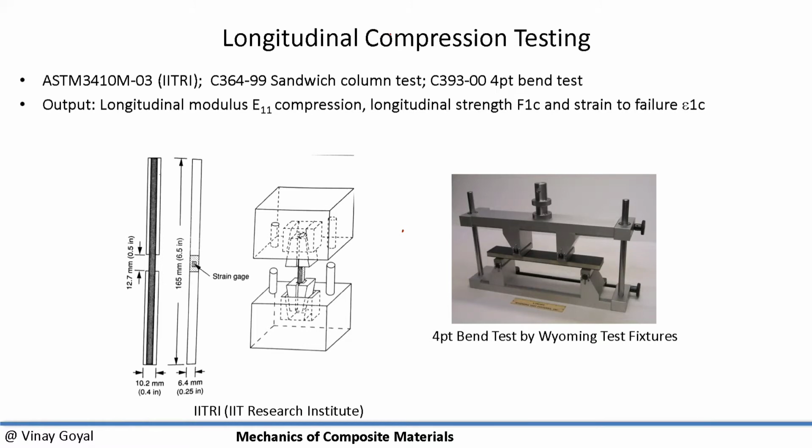Another approach that can be used to test is the 4-point bend test. The 4-point bend test can be very, very successful. What I'm doing there is applying a loading configuration here and here, and it is getting reacted here.